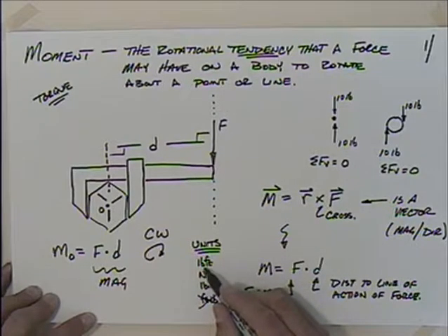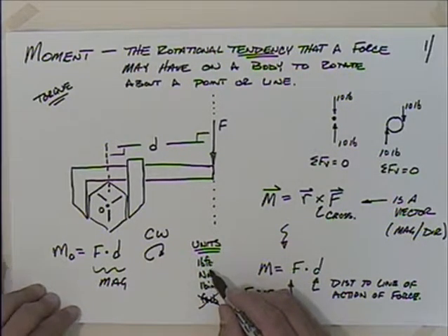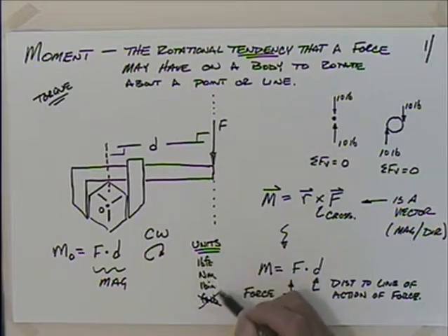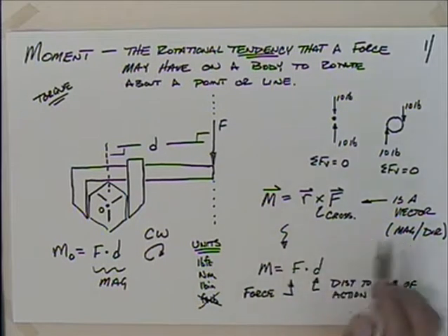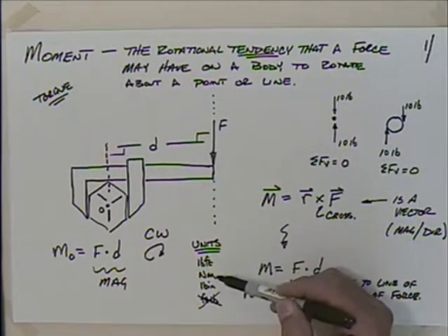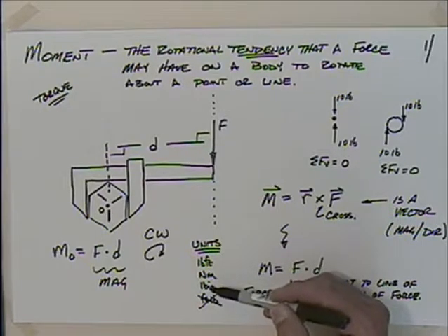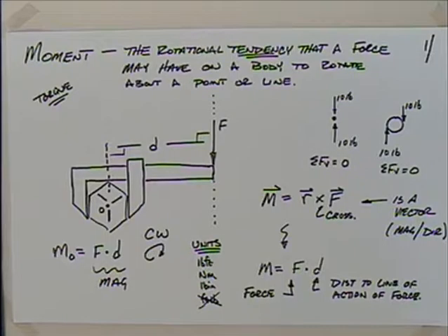So it is force times distance, but if you see someone talking and making a big deal about pound-feet versus foot-pounds, that's what's going on. Some other common units would be Newton meters in the metric system, or sometimes if we have a smaller value, it would be pound inches. Maybe you've heard them say that something needs to be tightened up to a certain amount of pound-feet or pound inches, and that's what you have going on there.